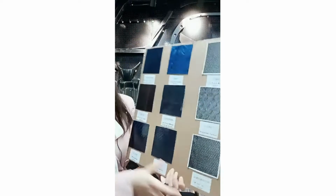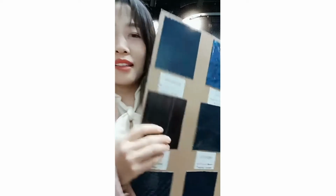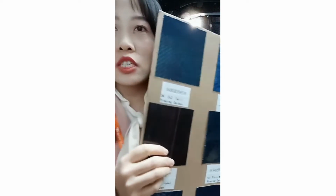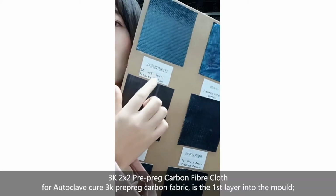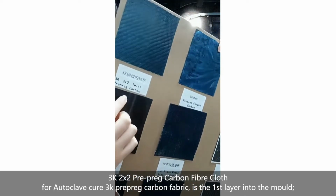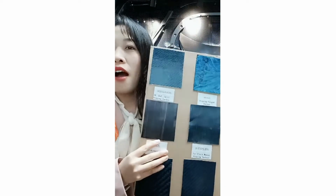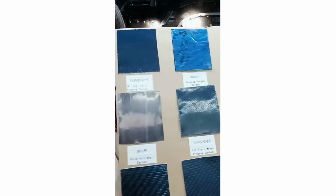When you look at the product name for carbon fiber, maybe like this, in our description or online descriptions, it will have a number followed by the letter K. That number will typically be 3K, 6K or 12K. What that refers to is how many thousands of filaments are in the tow that the particular fabric is made from.